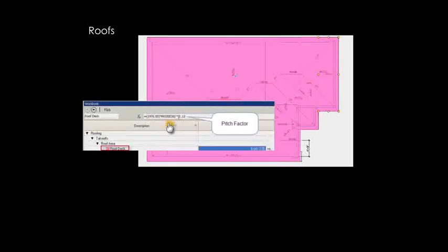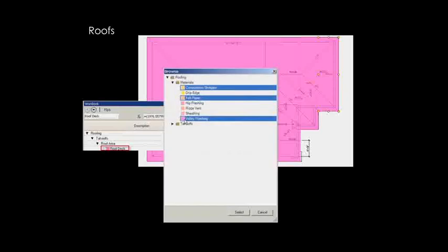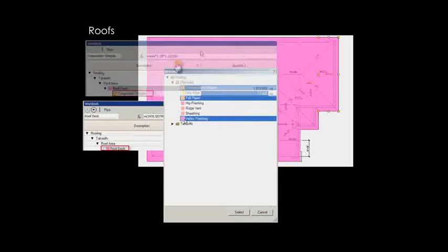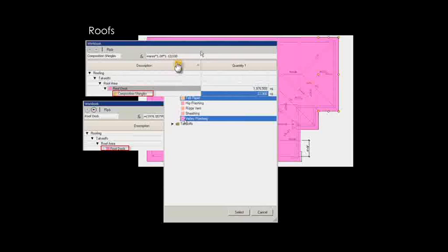You name it. You can find out the pitch factor and then just simply add it as part of a formula, and it's already part of the roof deck. You can assign it, and any other things that you want to quantify, flashing, felt paper, and so forth. If it's already built in the catalog, it's a matter of you sketching, activating the layer from the catalog,